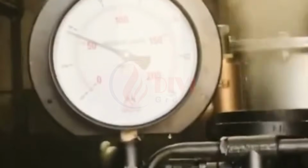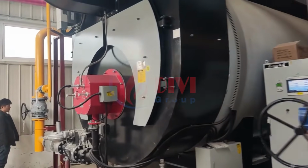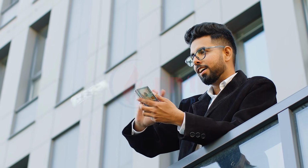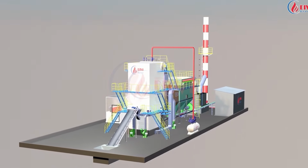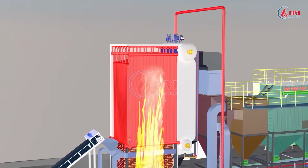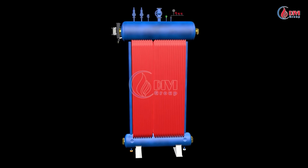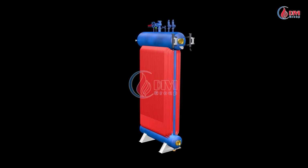Did you know? 95% of factories in Vietnam are using wet steam without realizing it, causing businesses to waste around 100 million Vietnamese dong each year just because the steam isn't dry. The cause isn't the operators. The real issue lies in the boiler's design, specifically the small steam drum and water pipes, along with improper feedwater arrangement. Most boilers on the market experience this problem.